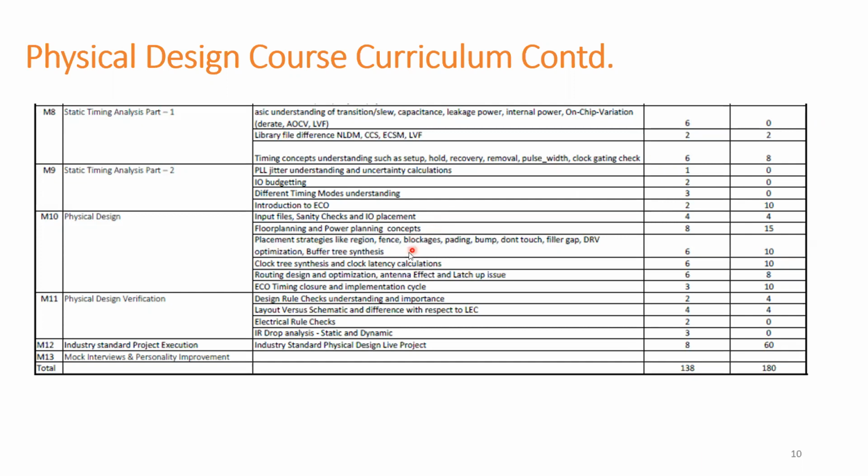We will study clock tree synthesis also, clock latency calculations, clock skew, and insertion delay. Once CTS is done, we will study routing of the design and optimization, antenna effect, latch up, etc. We will also cover ECO repairs: how the ECOs are generated, how the timing closure is done, how to write the manual timing ECOs, and how to generate the timing ECOs using the tool. Everything will be covered as a part of physical design in module 10.